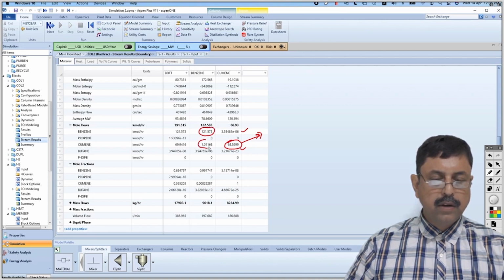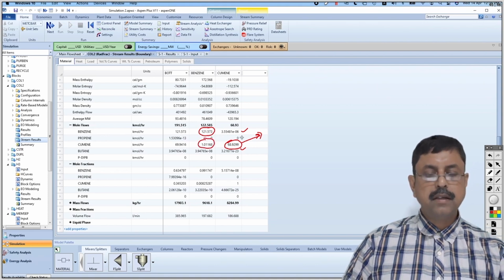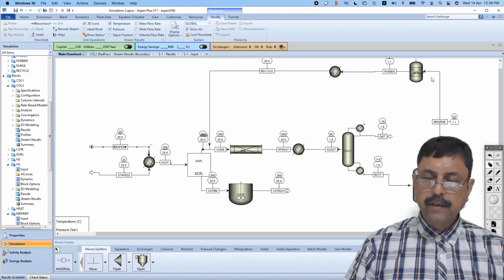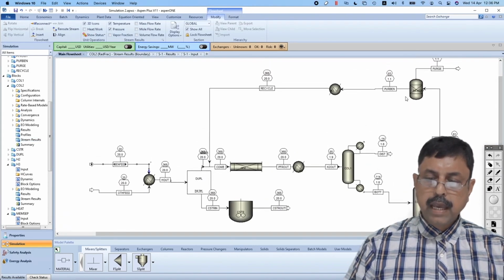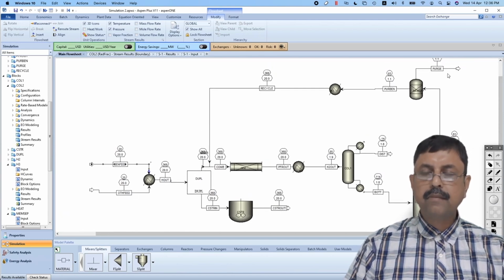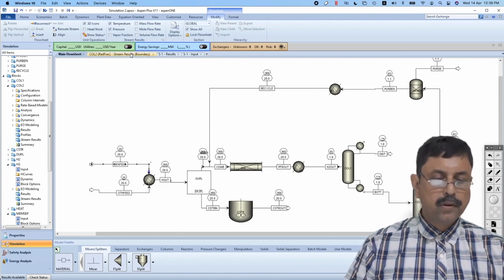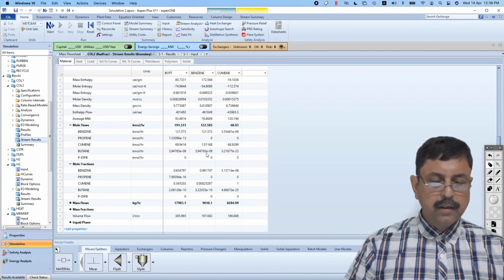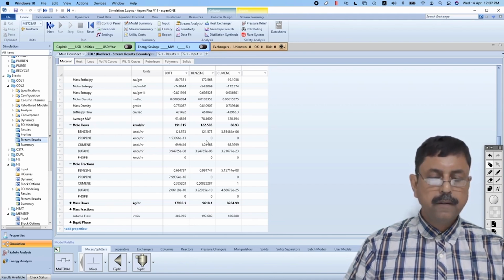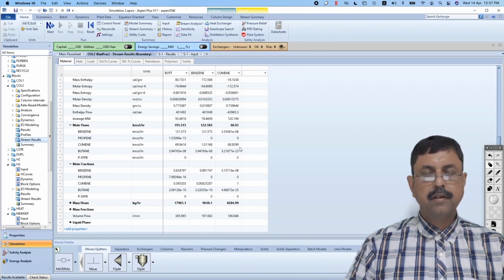And in the bargain, you are losing 1.01168 kilomole per hour of cumene through the purge, because this benzene line is passed through the membrane separation unit and pure benzene is being sent over here. The rest of the thing is purged. So cumene is being purged over here, but the rest you can obtain.